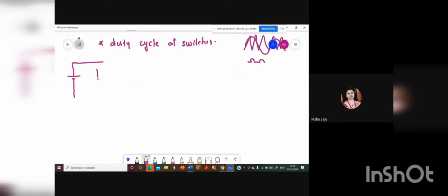I'm drawing the structure, and definitely it is a bidirectional switch. Bidirectional switch in the sense that once the switch is on, the current continues along this path, and in the other direction, if it goes to the source, it will use this path through the diode. Okay. So here you will have a diode combination also. This corresponds to the first leg.